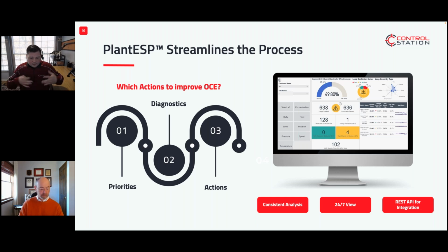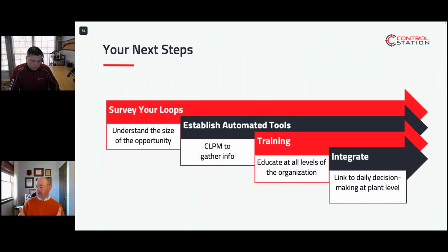What are some of the next steps, or the things that customers can do to get started and take a look at this? Sure. I think if you're in this webinar and you're thinking, oh boy, this sounds like a lot, I've got to do the software and the services and all of this stuff to get going, the shorter answer is no, you don't. You can get started right away by understanding how big the opportunity is at your plant. If you don't already know what percentage of your loops are running in manual today, take a notepad or your phone out to the control room if you can, and do a quick survey.